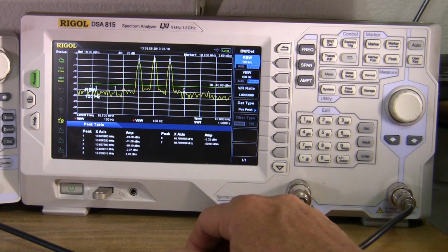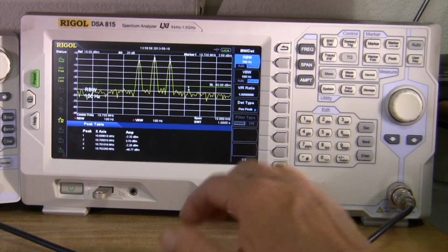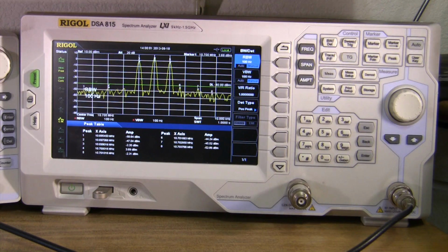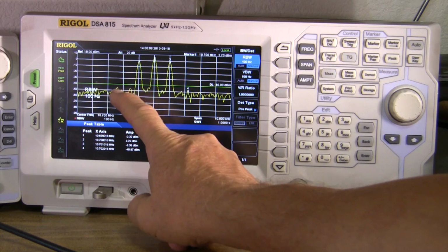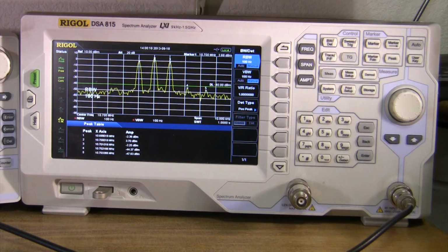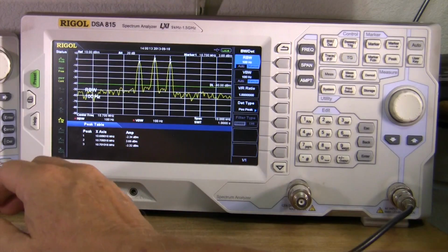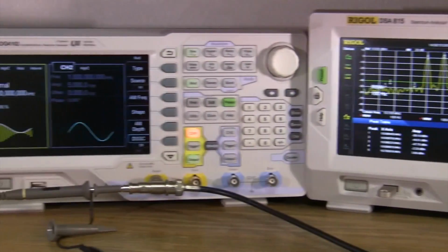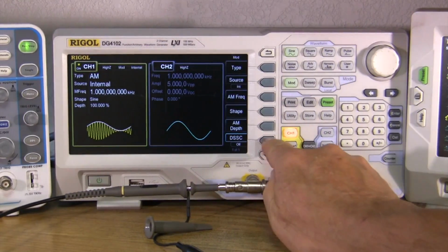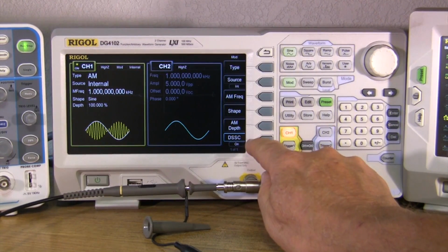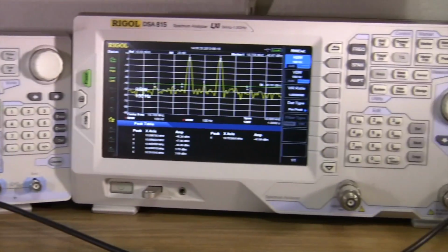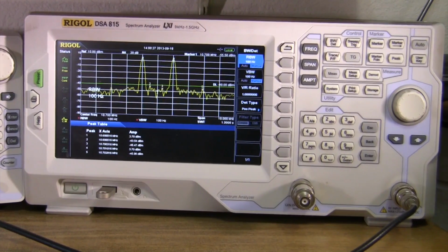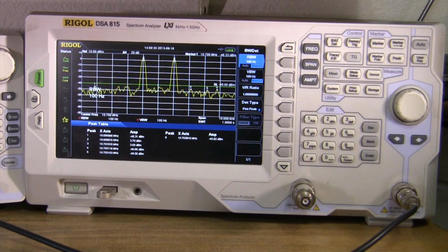And so just something to note, you've probably got to use the scope to measure what you're doing. I would also like to note that these are all below 40 dB down, below this. And the other thing, I'll put this back on over here to DSC, come back over here. Let's see if we can get 10 dBm per tone.